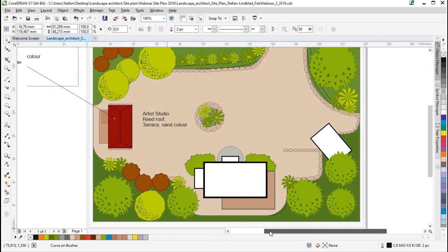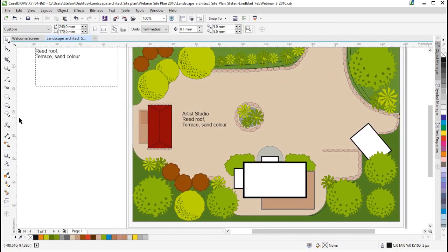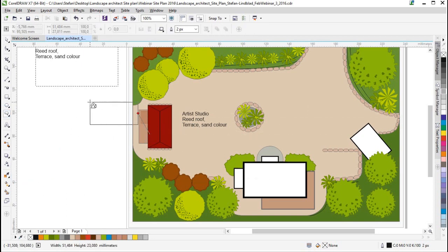But anyway, another thing that we have is also the call-out shapes, that I think is quite good sometimes for certain types of technical illustrations that I do. So I just drag a little frame there with the call-out shapes, and you can select from here and then choose the type of call-out shape, a speech bubble kind of, and then just grab with the shape tool. You grab the little yellow dot there and drag it to the object which you want to connect, so to speak. And these are not like the connector tool. This is just a call-out shape.